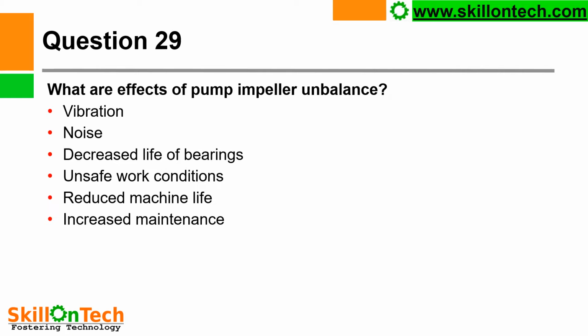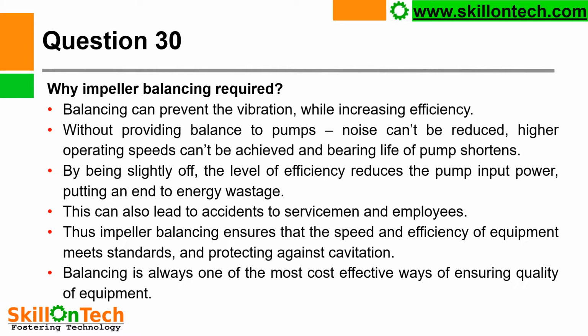What are the effects of pump impeller unbalance? Vibration, noise, decreased life of bearings, unsafe work conditions, reduced machine life, increased maintenance. So let us understand why impeller balancing is required. Balancing can prevent the vibration while increasing efficiency. So impeller balancing will reduce your vibrations and it will increase the pump efficiency.